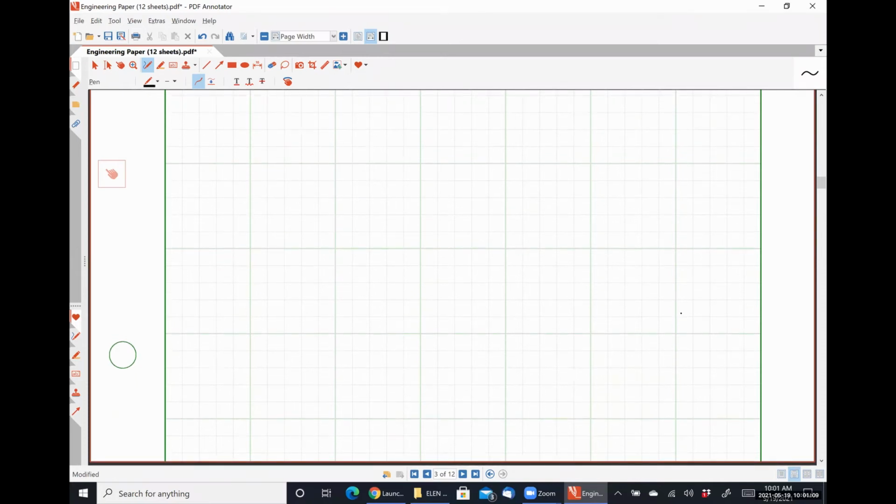So to be clear, what we're looking at is effectively just this portion of our circuit. Here is Vy, which is the output of this stage, and here is where Vx is applied, right? So if I were to draw my small signal model for this guy, my gate is an AC ground. This is my gate for M1.